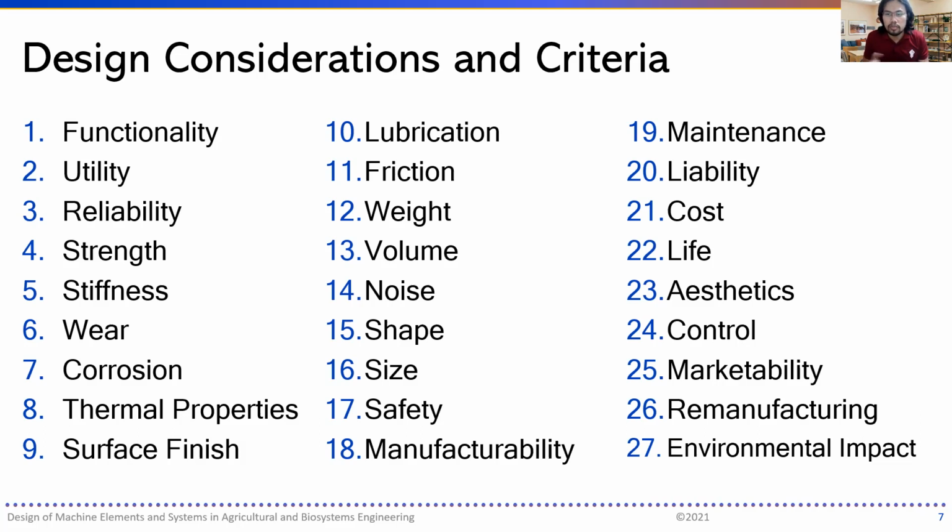There's stiffness. While metals are strong, they can still be workable, they can be worked on. Stiffness is the resistance to bending due to applied force. Fatigue is the measure of the ability to resist the action of loading, such as a force repeatedly introduced. And then there's corrosion, a chemical property identifying the resistance to chemical reaction to a corrosive chemical.